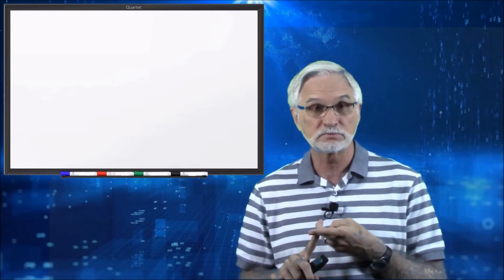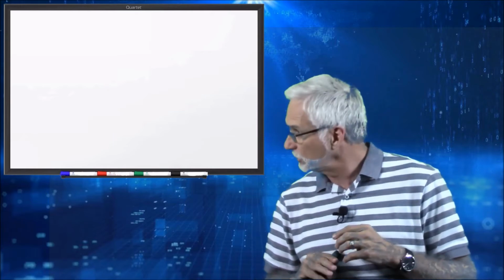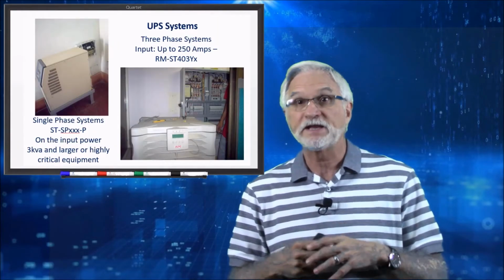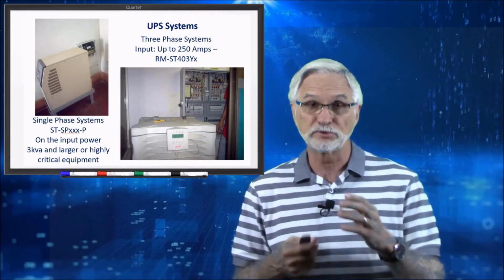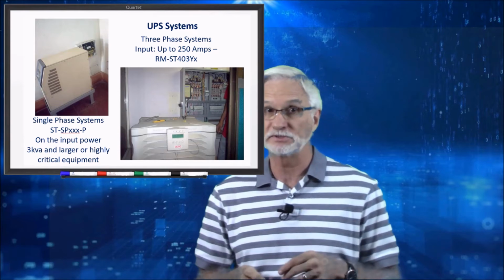Two reasons. Number one, that is a smart electronic piece of equipment, and it's got microprocessors in it to do its operations. Secondly, we found in our investigations that a significant amount of transient voltage between phase and ground can go directly to the connected load. So by protecting the input, we're able to enhance the life of the equipment. We're able to reduce its maintenance and downtime by doing so.